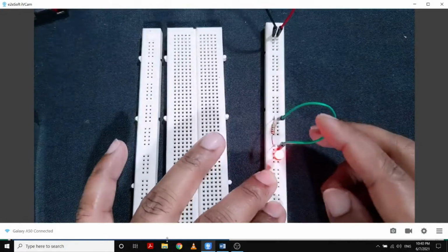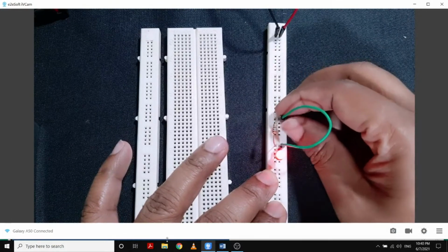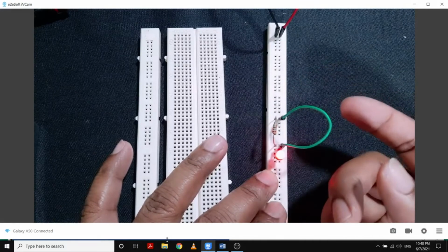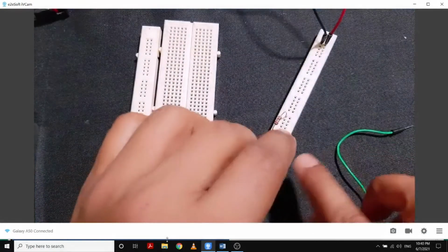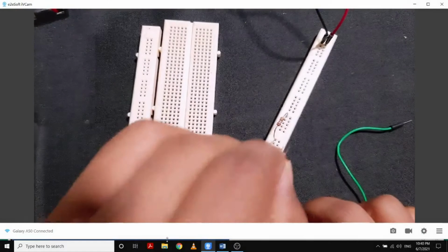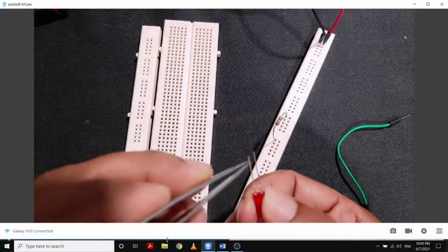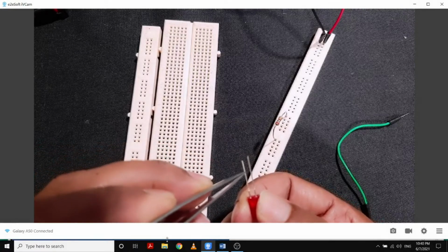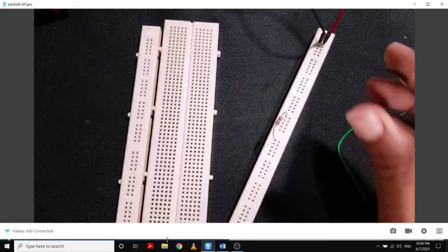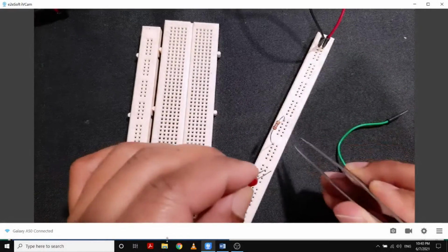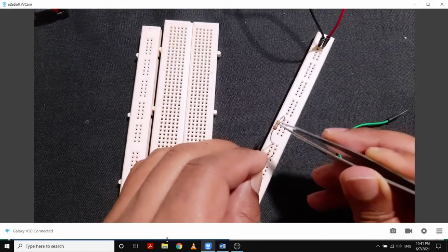Sometimes these breadboard wires come as broken ones, internally broken, right? So therefore check all the wires, right? And by using this, so this is the LED. So LED bulb, you have negative and positive terminal difference here also, right? So the little bit lengthy one is positive, short terminal is negative, right? So therefore when you fix this, now all the positive current is coming in this way. So then you have to plug this positive current into positive line, right? The shorter one, the negative current through resistor, right?